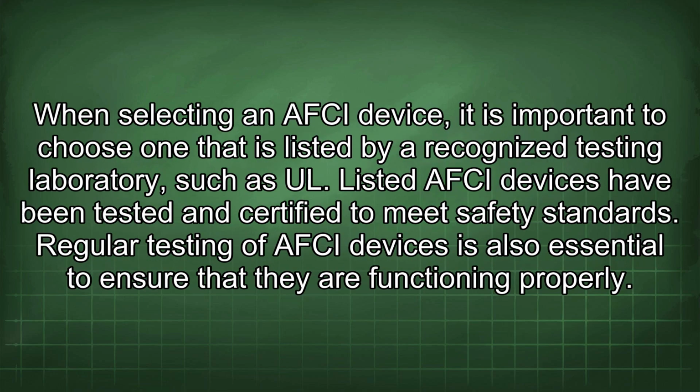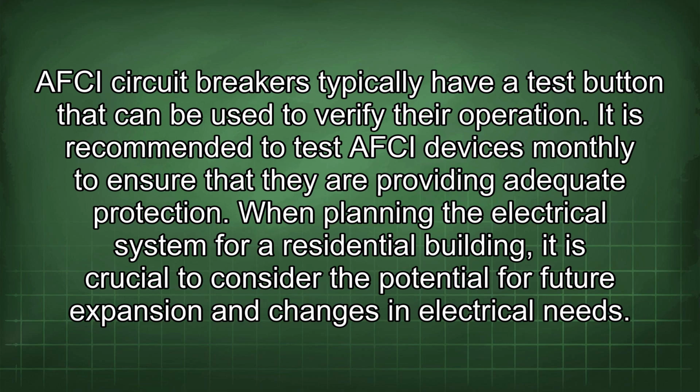When selecting an AFCI device, it is important to choose one that is listed by a recognized testing laboratory, such as UL. Listed AFCI devices have been tested and certified to meet safety standards. Regular testing of AFCI devices is also essential to ensure that they are functioning properly. AFCI circuit breakers typically have a test button that can be used to verify their operation. It is recommended to test AFCI devices monthly to ensure that they are providing adequate protection.